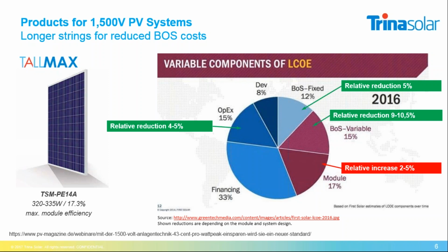That means you can use it, and there are also some string inverters available, so you can start to build systems in a range of, let's say, 30 to 60 kilowatt as minimum size. And then you have the advantages of higher voltages, reduced system costs, and better, that means lower, LCOE.